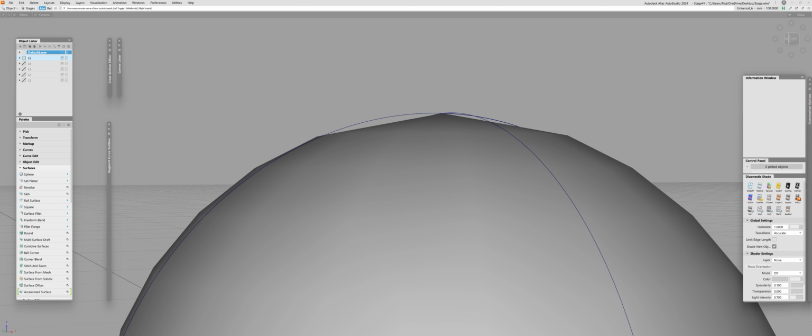up the shader, you will notice that in this panel there is no such thing as a quality slider. Instead, there are two others. One of them called tolerance, and another one called tessellator. It's set to accurate. Now, the reason why there is no quality slider is, well, how can it be? Polynomials are polynomials. You can't make them less accurate.